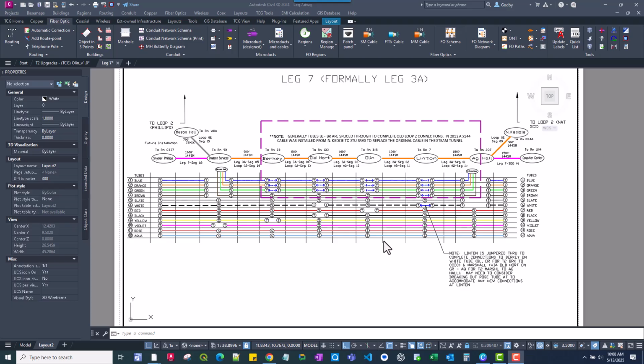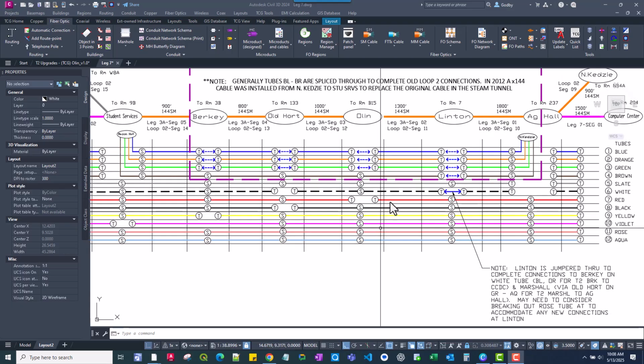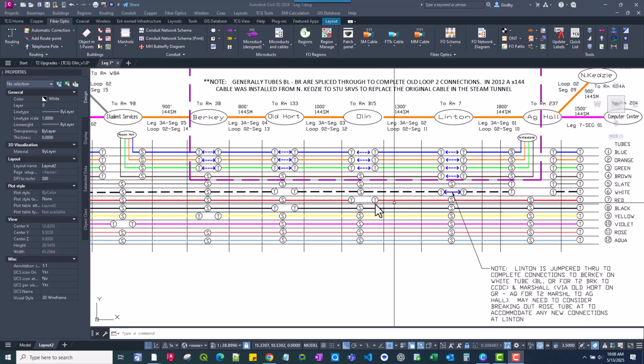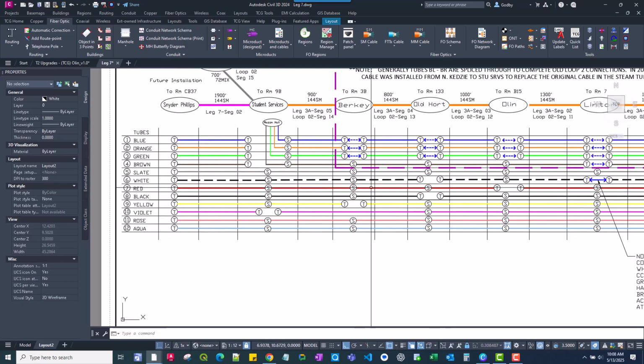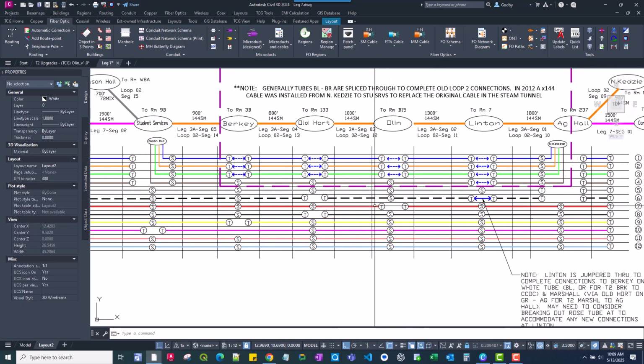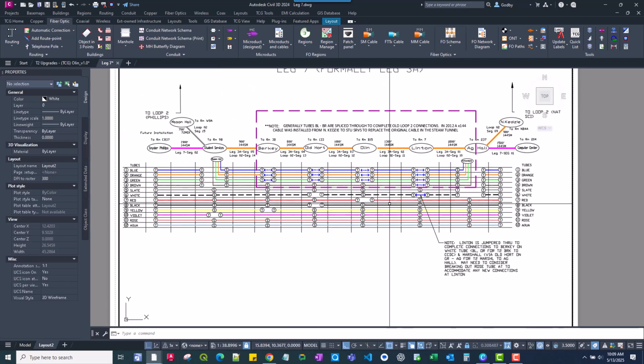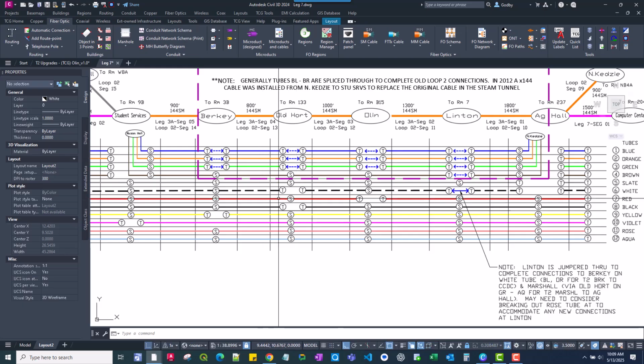So here's a look at the fiber splicing of the existing fiber plant, and we're dealing with Olin, so we see that it is terminated in Olin, but through the other buildings on the red tube it's already spliced all the way through. So we don't need to visit. And as far as this exam or design, because this is just to get the circuit from Olin to the two T1 buildings, all we just need to do is show a splice on our diagram that the red tube splices through there.